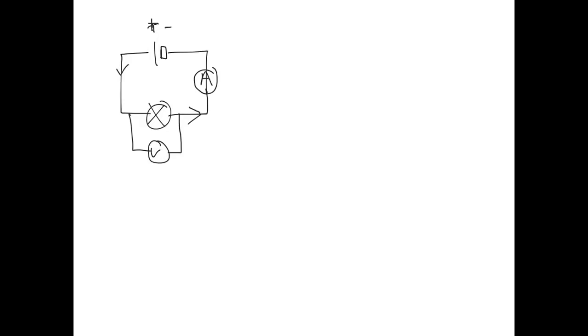Okay, next up is the difference between series and parallel circuits. So if I just draw a series circuit there, and say that the light bulb is a certain brightness, what we can do is add another bulb, like say we add it here, and it seems pretty obvious that the brightness of both bulbs will decrease, and if they're the same, then they'll be half as bright as they were initially, and that's because each electron that flows out of the cell has to flow through both of them and has to share its energy across both bulbs, so you find that they are dim.